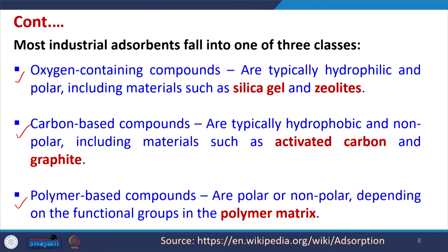We have to see this aspect, that they are hydrophilic, but sometimes we do not require hydrophilic, we require hydrophobic. Carbon based adsorbents can be better because they are hydrophobic, but they are non-polar. That means they will be able to adsorb everything and anything.